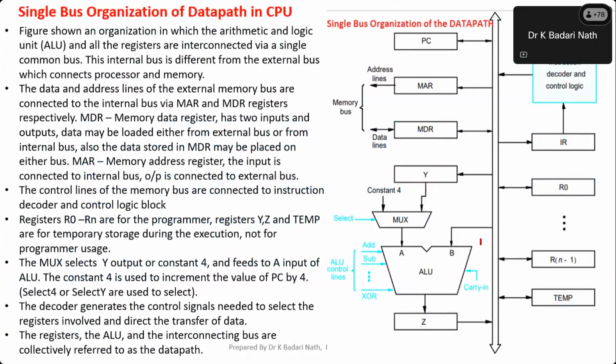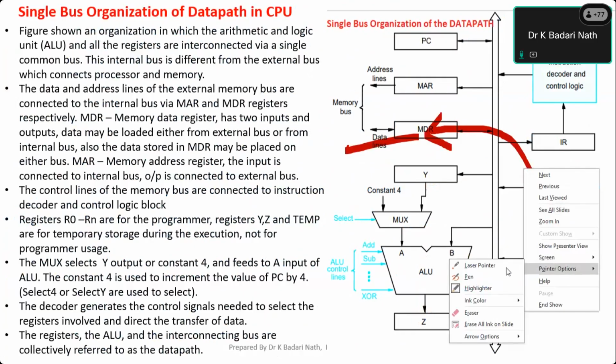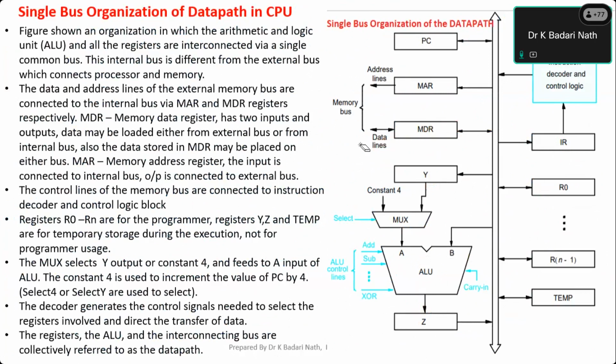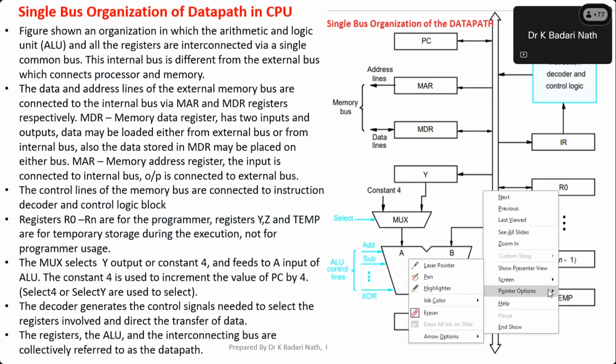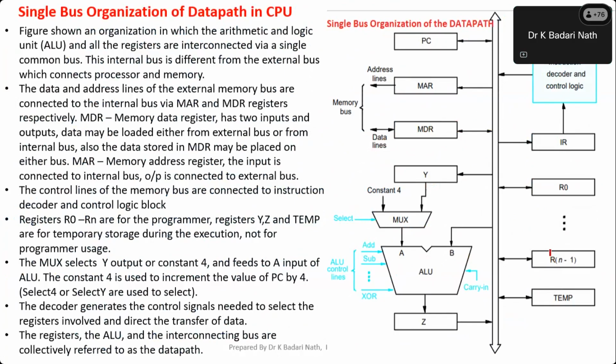Okay, so now we'll repeat. What is the first thing we'll do? I have to take the R1 contents and make the address available to the outside. Sorry, it's not the MDR register. It has to go to the MAR register. Whatever is in the register R1, it has to go to the MAR register, and that address should come out to the outside. So this is the first clock cycle. R1 out, MAR in, so that address comes here.